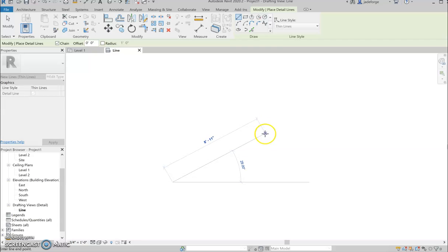And as you can see, you can start moving your cursor in any direction in the positive or towards the right. I can go up to my 45-degree angle. Yes, we can change the snaps on those just like in CAD to be able to get the angle exact. Right now, you can see that I have temporary dimensions up. The program has temporary dimensions up automatically.